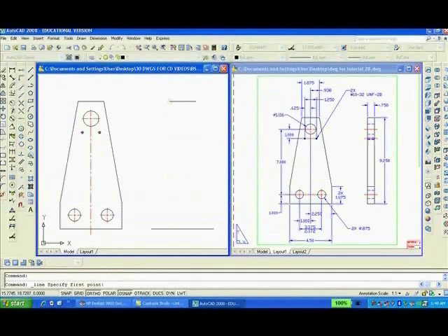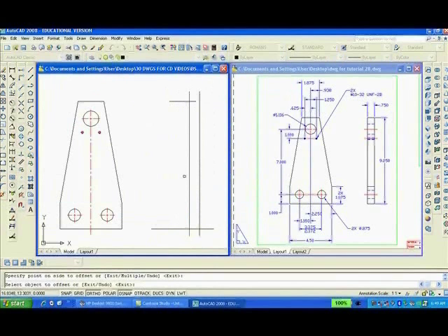another line, doesn't matter where, here. Then we're going to offset that line 0.75, and we'll use the fillet radius 0 again to clean up the intersections.